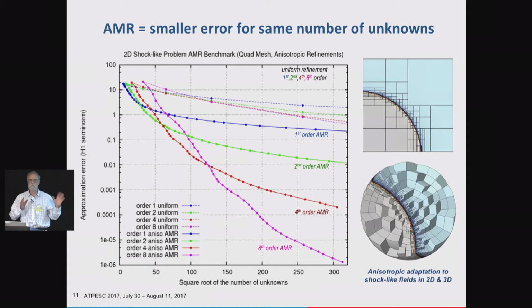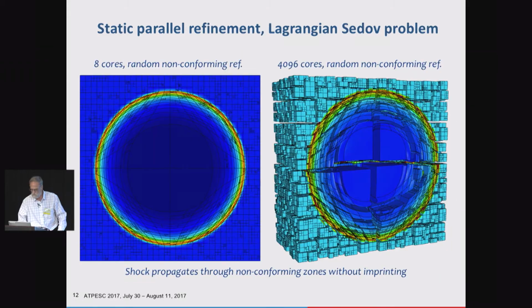So those are just some comparisons of the methodologies. Of course, there's prices to pay, as you have a lot of extra work in the meshing. These meshes can be adapted almost like that, whereas the mesh adaptation procedures that are conforming, that really deal fully with the geometry, are going to be more time consuming.